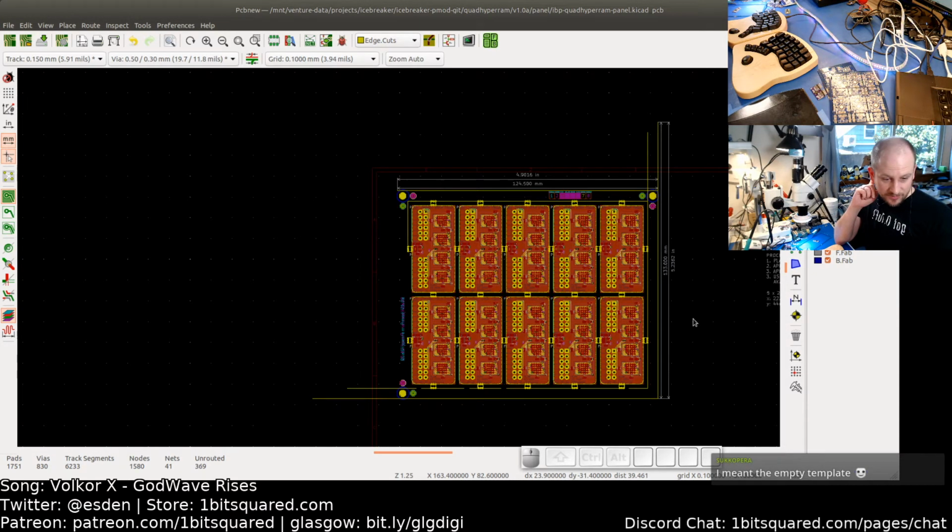Second question, do panels have a fixed size, or do they need to ask the manufacturer how big panels they're using? So there are several layers of panelization. Manufacturing panels at the PCB manufacturing plant are, I think, 24-inch square, something along those lines. So they are pretty chunky things.